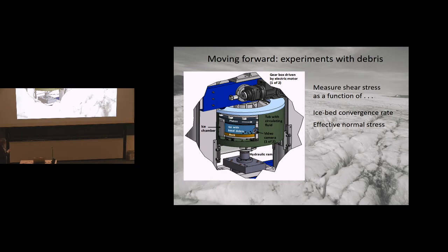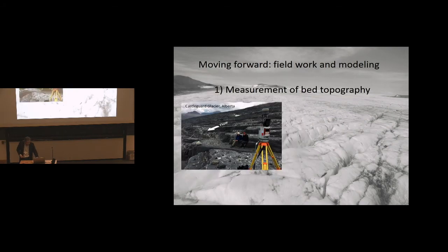What does that do? That ice motion around these clasts exerts a viscous drag on the clasts and presses them against the bed. And that is what we're learning is responsible for debris bed friction. And now that we're developing empirical rules for this, we can start to think about adding this in to a more realistic model of glacier sliding.